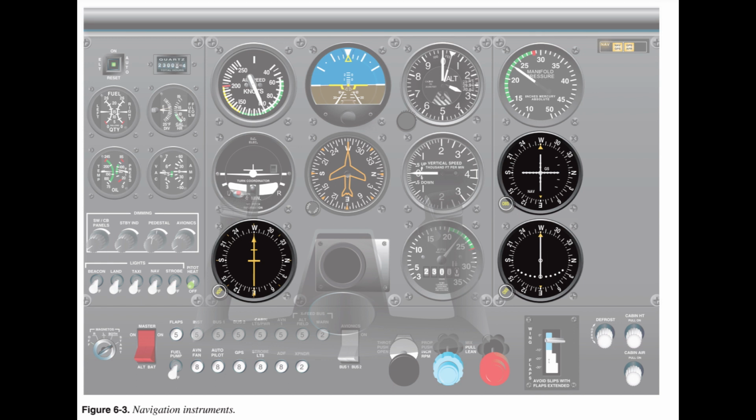Procedural steps in using control and performance. 1. Establish an attitude and power setting on the control instruments that results in the desired performance. Known or computed attitude changes and approximated power settings help to reduce the pilot's workload.